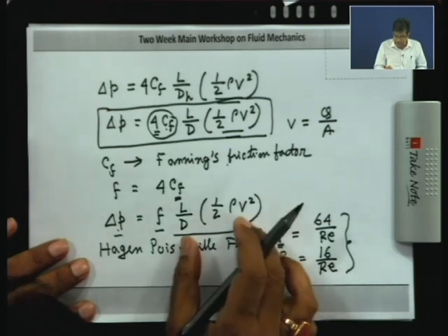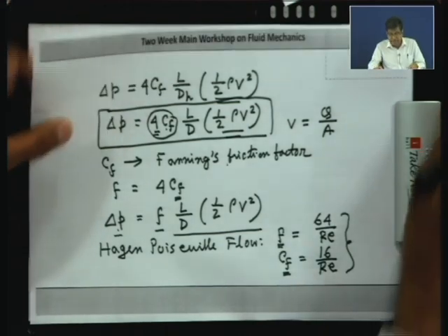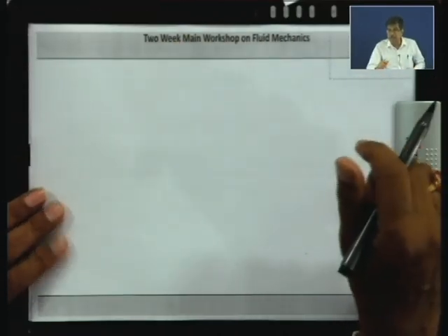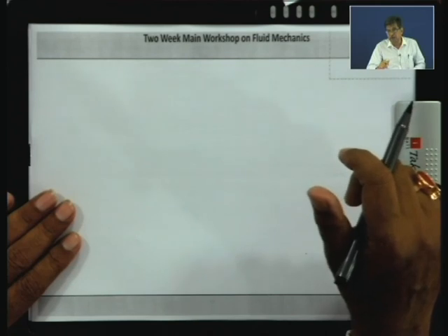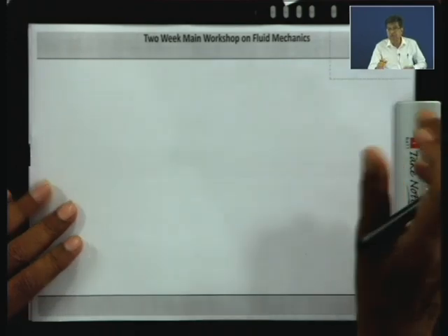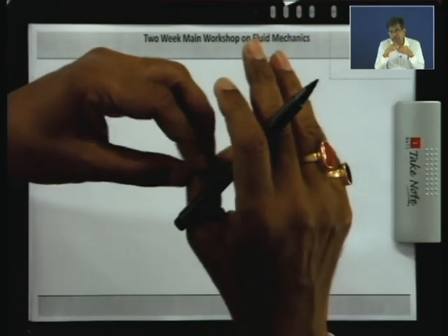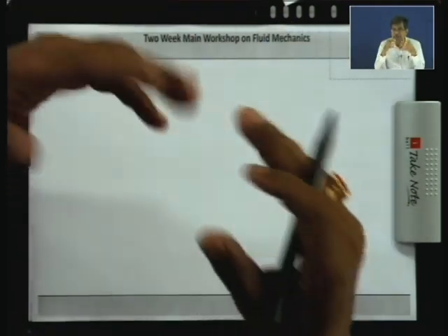For turbulent flow also we can develop a similar relationship with the help of turbulence models. But sometimes it is difficult to have a unique expression even from theory in the case of turbulent flow, because it varies from type to type of turbulent flow and the level of turbulence. So, in turbulent flow, we depend mostly on empirical equations, and even if it is provided by the theories of turbulent flow, some empirical information is required regarding the wall functions or some empirical constants used in the turbulence models.